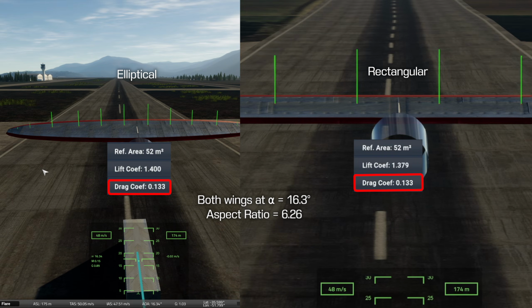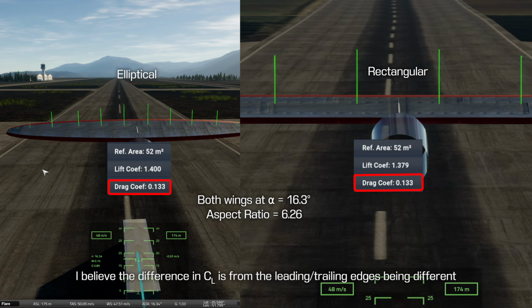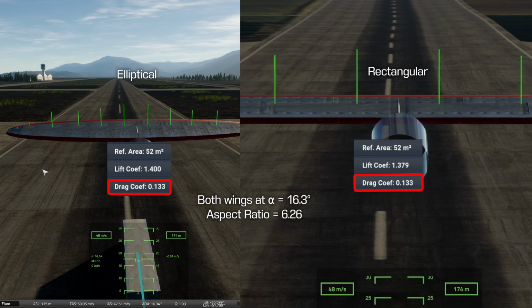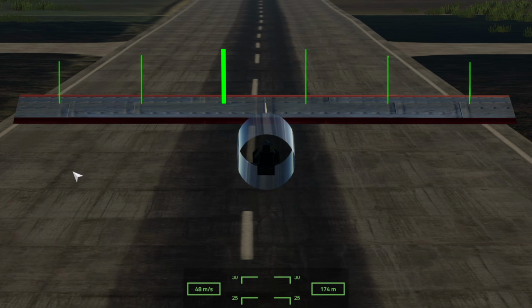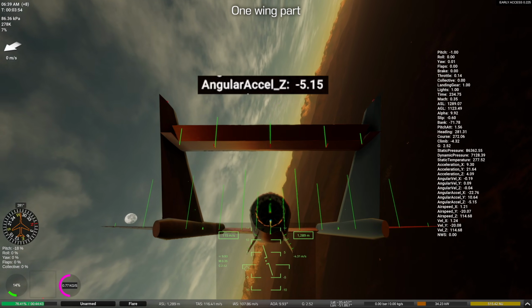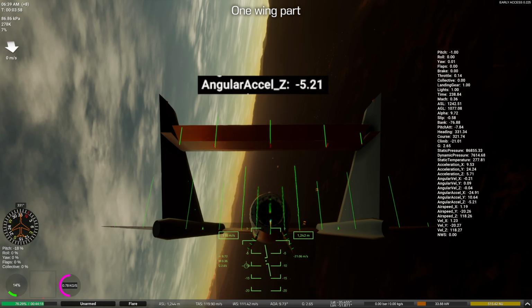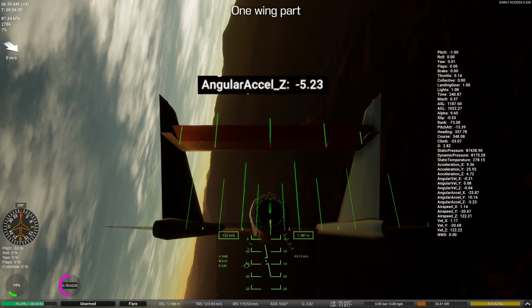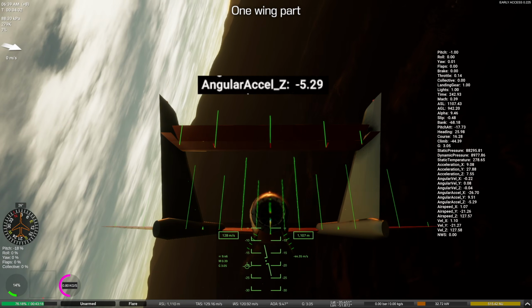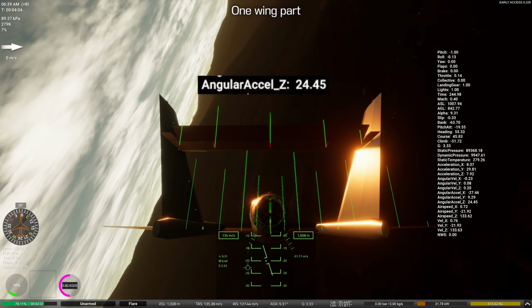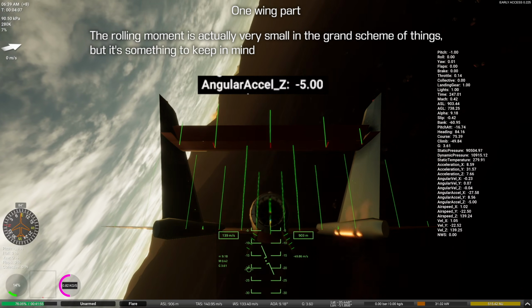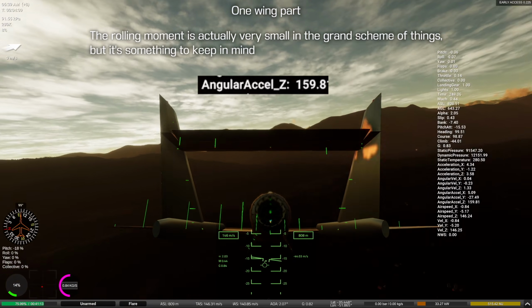At the time of writing, the taper ratio does not seem to have an effect on wing efficiency in Flyout, although some form of lift distribution is modeled such that the root of a rectangular wing generates more lift than the outboard sections. Because of this, one should be mindful when making certain control setups, such as twin boom aircraft with a central wing as the horizontal stabilizer. Just using one wing part will have an uneven lift distribution and will roll slightly as a result. It is recommended to use two mirrored wing parts instead.